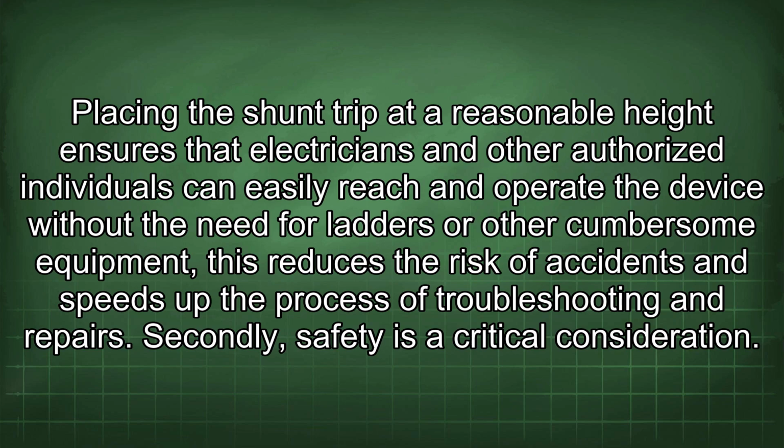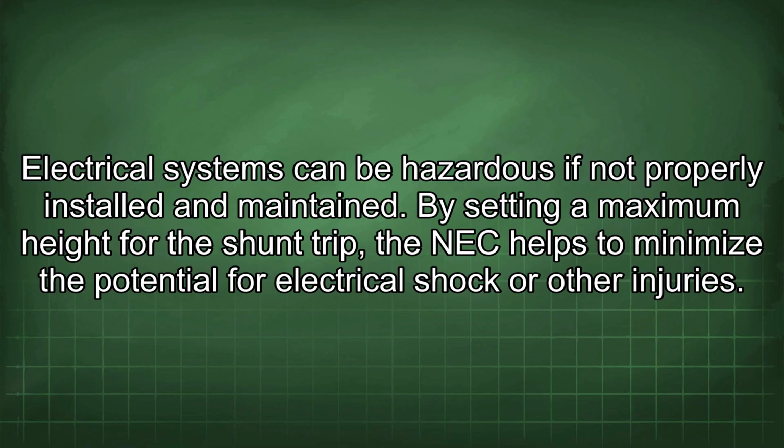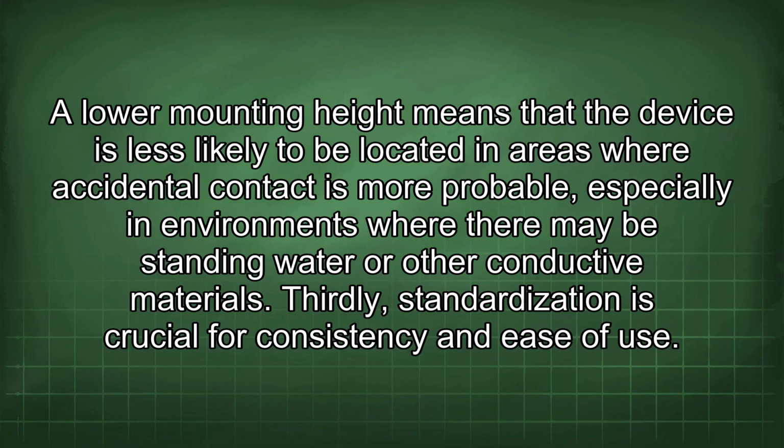Secondly, safety is a critical consideration. Electrical systems can be hazardous if not properly installed and maintained. By setting a maximum height for the shunt trip, the NEC helps to minimize the potential for electrical shock or other injuries. A lower mounting height means that the device is less likely to be located in areas where accidental contact is more probable, especially in environments where there may be standing water or other conductive materials.